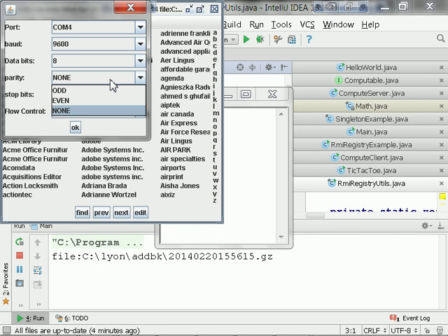You compute the parity by using the exclusive OR operation across all the bits in parallel. So you take all the bits, you do an exclusive OR, and then that gives you your parity output. If you want even parity, you put an inverter on it and use an exclusive NOR.